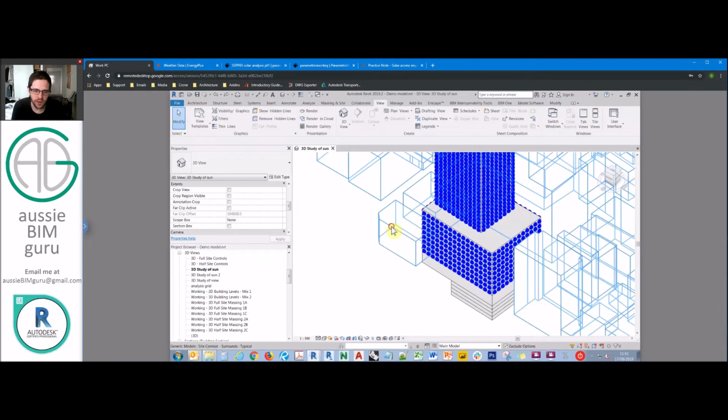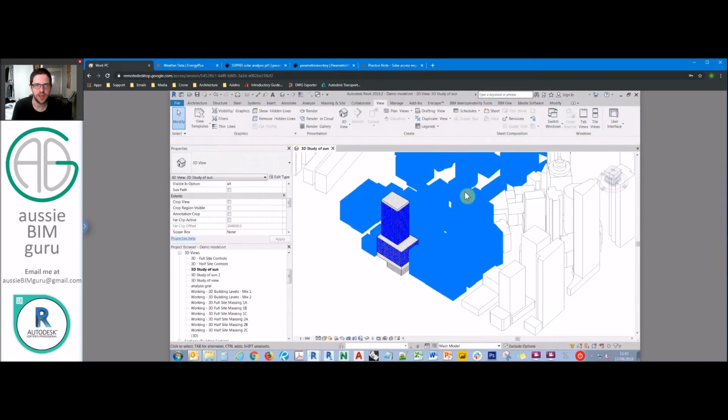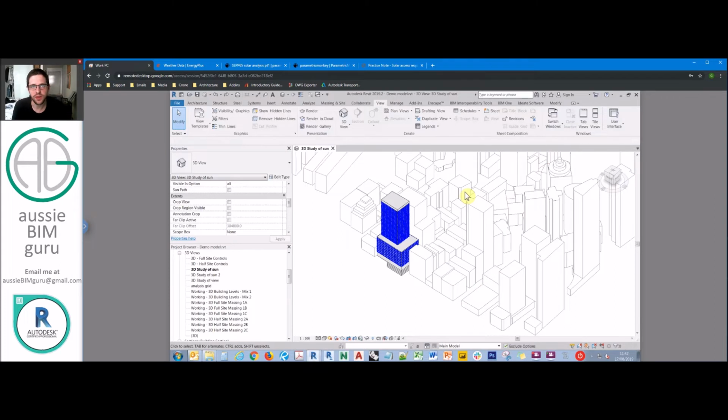But be careful with this shared parameter on other families. So for example, this one here, if I told this it had 1 hour of sun, you can see it overrides this element as well. You could refine your filter to only apply to sensors if you wanted to. Okay, but now we're actually going to work with Dynamo, so we're going to start building our script.